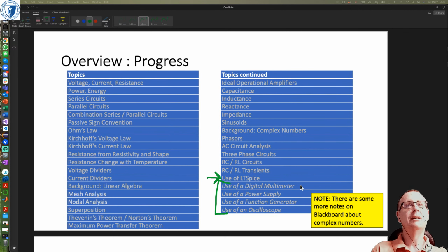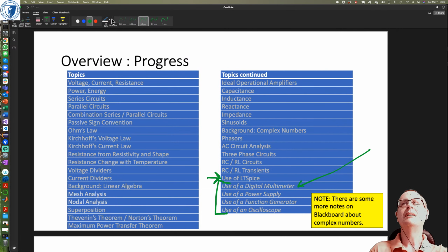So the multimeter is basically the thing that measures the voltages and the currents. And one thing you should get out of this is that on a multimeter there are three inputs. There are two red inputs, and there's one black input, right? And this red input usually has a V and an omega beside it, and this input usually has an I beside it. Anybody got any idea why?